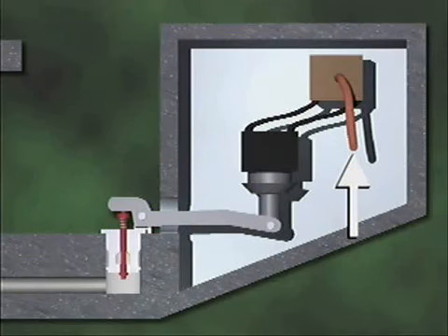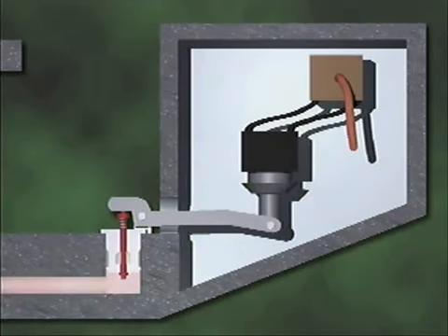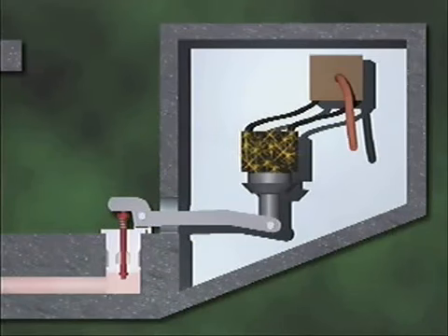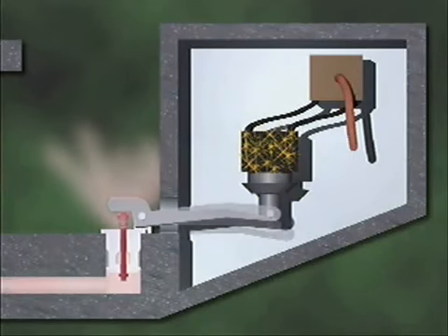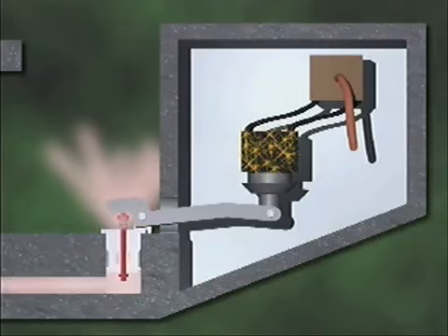A pressure-sensing tube in the pilot device detects increases in system pressure, and when system pressure reaches the predetermined level, the pressure-sensing tube activates an electrical relay. The electrical relay closes an electrical circuit and energizes a solenoid. The solenoid then lifts a pilot valve, and the excess pressure is relieved.